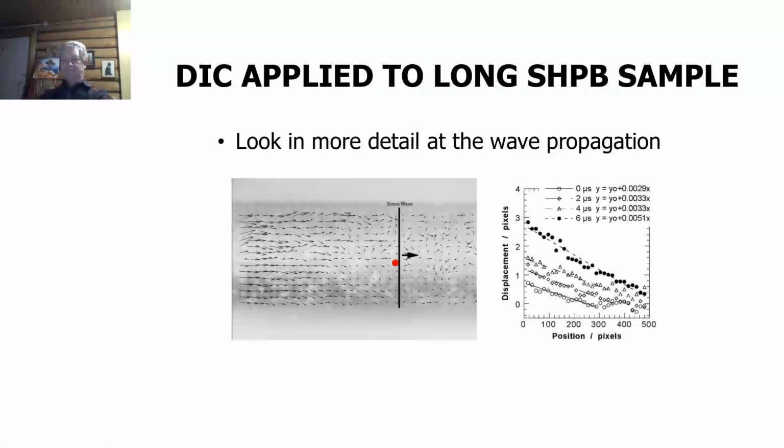Okay, but is that okay? Yeah. But you say that results are in agreement. But as I remember, when you calculate stress and strain fields from Hopkinson bar equations, you suppose that the strain field is uniform, but in reality it is not.